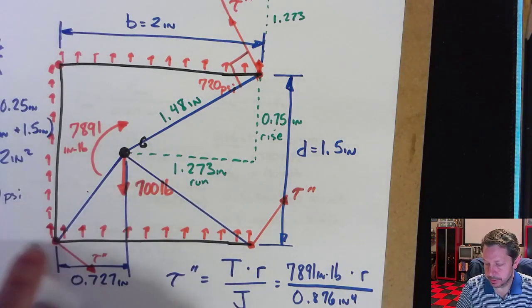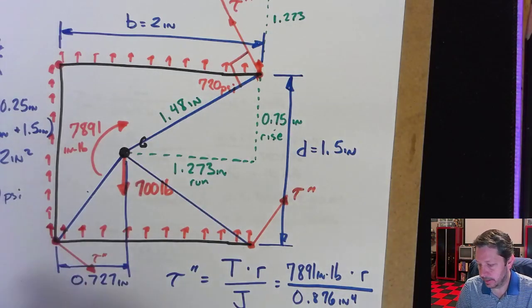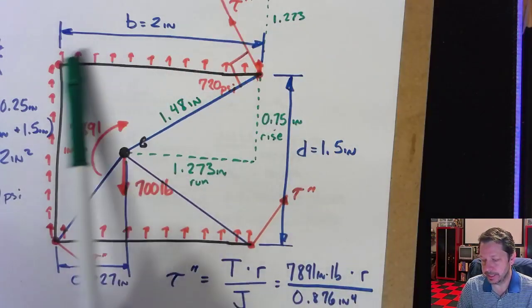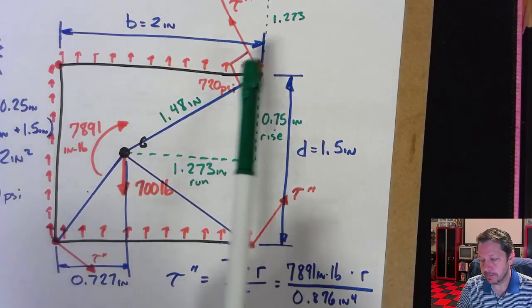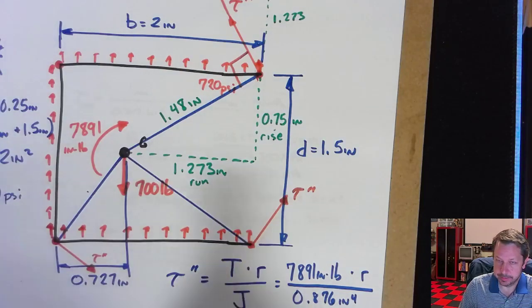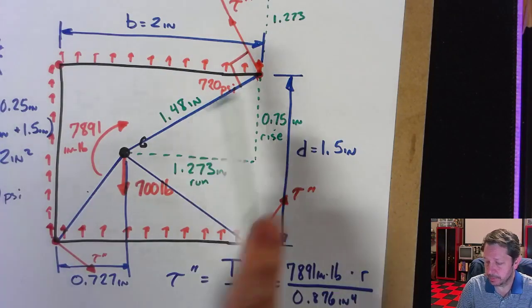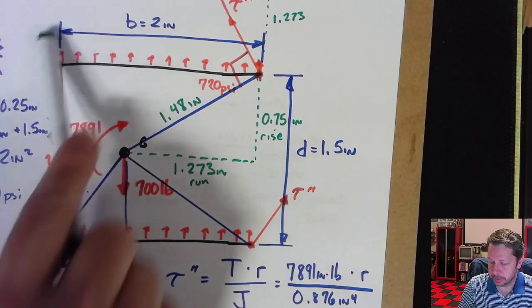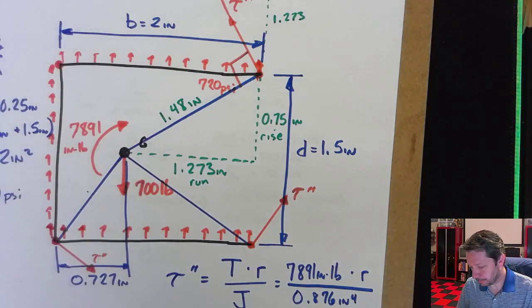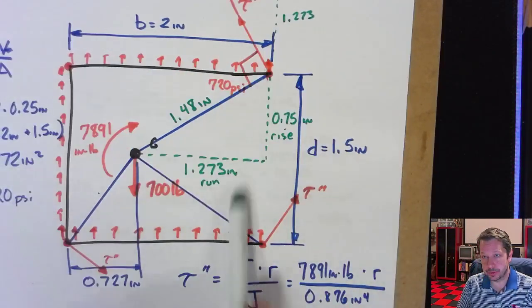And so we know that they are worst case scenarios, and we don't have to worry about, or at least in this case we don't, and you normally don't have to worry about this, the weld changing size. Normally you do have the same size weld all the way around. Whereas with the bolts, remember we had a bolt pattern where there was a larger bolt and two smaller bolts, and we did have to worry about the smaller bolts. You don't really have to worry about that in this weld setup. All right, so that is the torsional one.